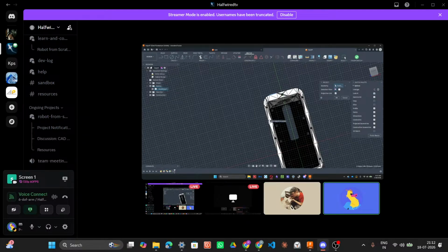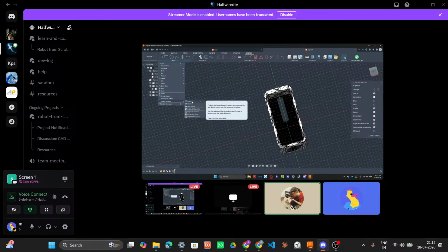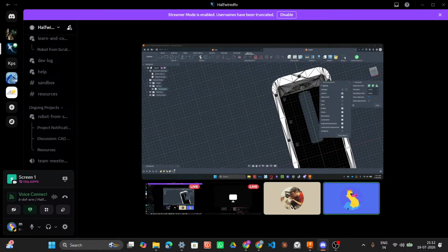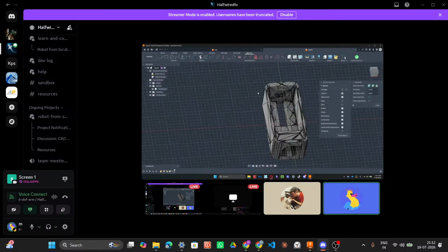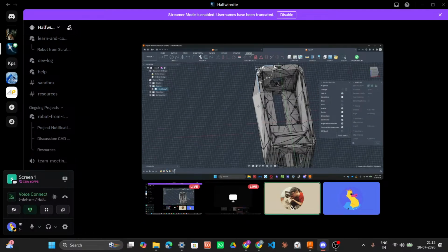Can you show me the project option? Where is it in the sketch create menu? Oh yeah, I just hit P, but it's in Create. Project includes. If you just hit P, it gives you the default project. If you want the intersection that I did earlier, then you have to actually come in and click it, because there's no hotkey. But intersection just copies everything that's in between the plane, right?